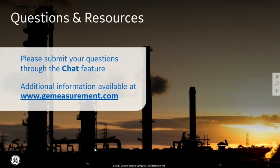Just to add to that a little bit, I saw another question in the Q&A list about whether the instrument is pre-programmed for certain probes. We do, in Create, provide a list of some of the most common probes that have the native Mentor connector on them. When you select one in the list as you're beginning to plan your app, it will pre-populate the critical parameters that describe that probe, like number of elements, element pitch, elevation, and the frequency of the probe. Those are preset for you from a database of known probes. But you can pick any probe. It doesn't have to be one that we make, and you can enter those parameters manually, both with controls on the instrument itself or in Create as you build the app. You can build your app targeting a particular probe, even from another manufacturer. So it's a very versatile system that way.